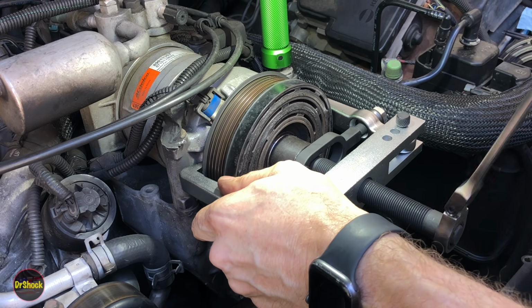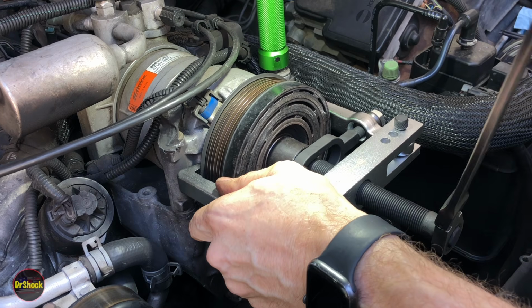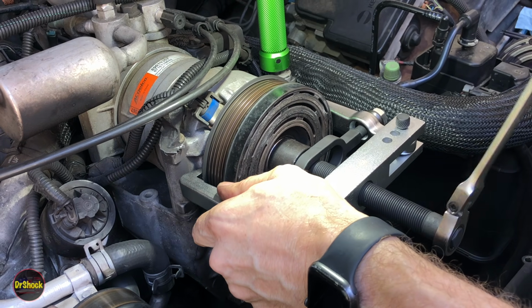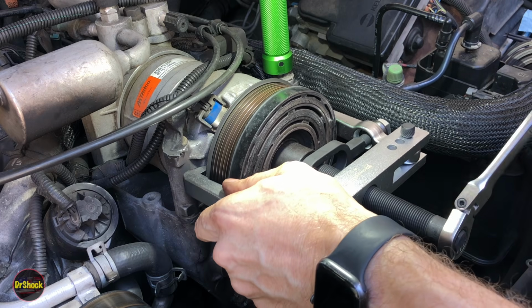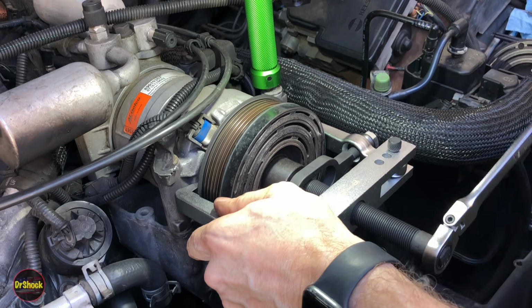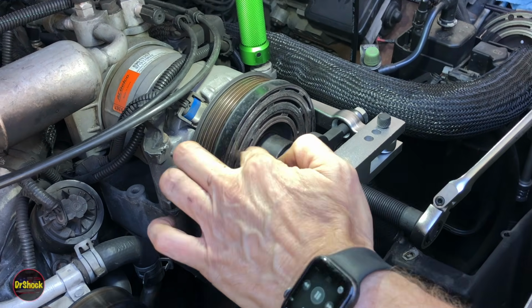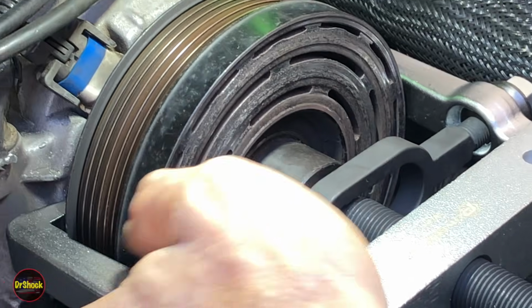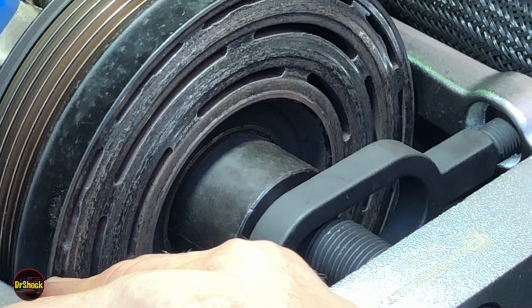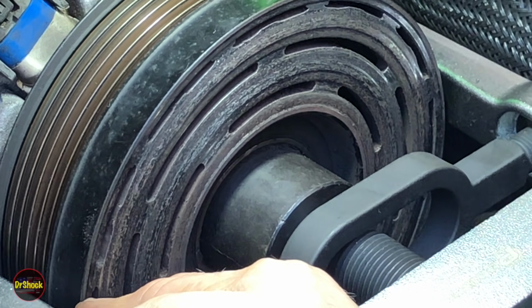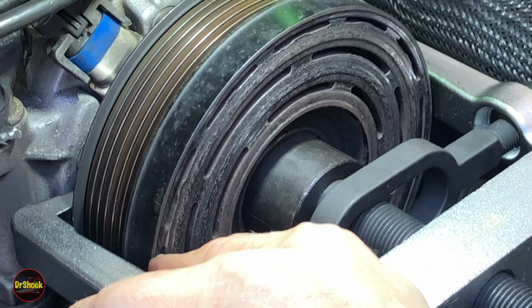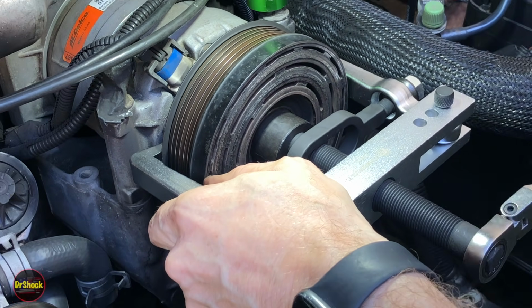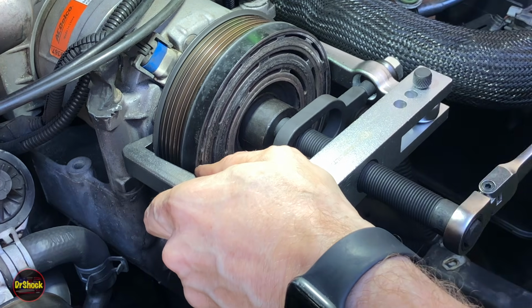And again, if you feel like you need to, you can put some grease in the forcing screw right here. I don't really feel like that's needed on this particular type of application, just like with the one we did with the rotor. You can see we're closing off the gap we had with the aluminum as she comes off. And that pilot is small enough that the pulley's just going to slide right over it.